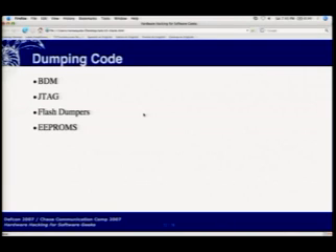Basic JTAG won't let you do debug. It won't let you step the clock one step at a time. It won't let you access the registers. It will, however, let you set or clear the state of any pin around the device. Basically, the JTAG talks to a chain of shift registers that sit between the actual metal pin on the outside of the circuit and the silicon inside the device, and allow you to change these pin states without the chip itself actually running.